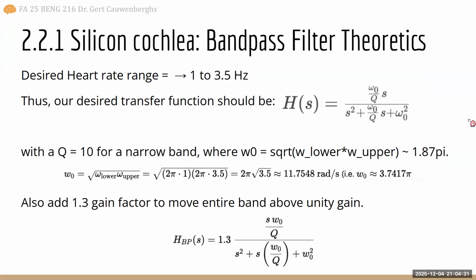For the design of the bandpass filter, we wanted to select for the desired heart rate range. In the case of resting heart rate, as Vivas mentioned previously, it's around 1 to 1.6 hertz, but we wanted to allow the heart to also speed up, for situations when the patient is exercising or otherwise actually does want a higher heart rate to deliver oxygen faster.